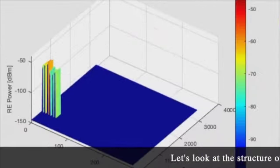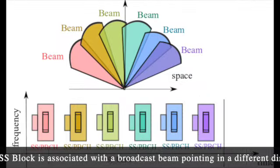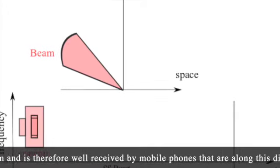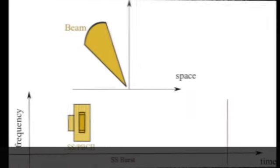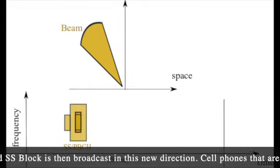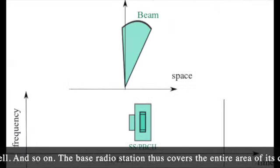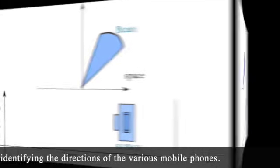Let's look at the structure of the SSBs. Each SS block is associated with a broadcast beam pointing in a different direction. For example, the first SSB is associated with this beam, and is therefore well received by mobile phones that are along this direction. The second SS block is then broadcast in this new direction. Cell phones that are along this new direction will receive this SS block well. And so on. The base radio station thus covers the entire area of its competence, identifying the directions of the various mobile phones.